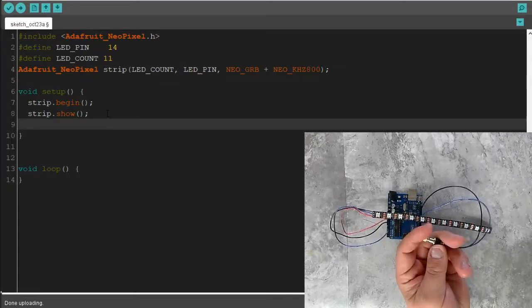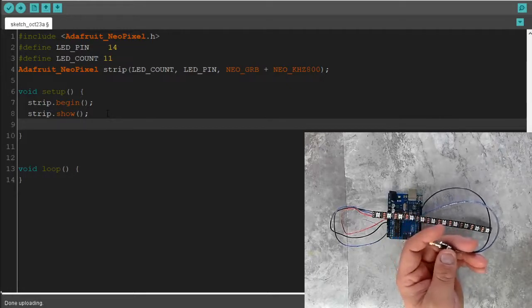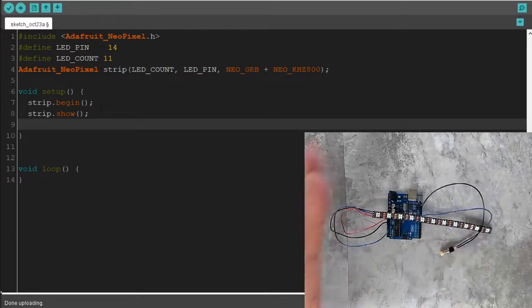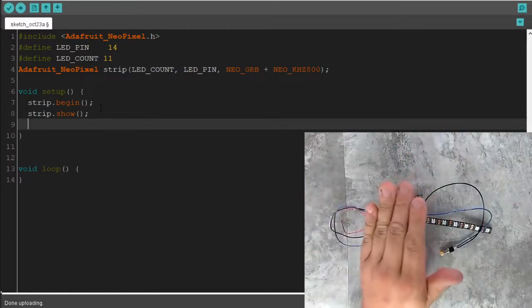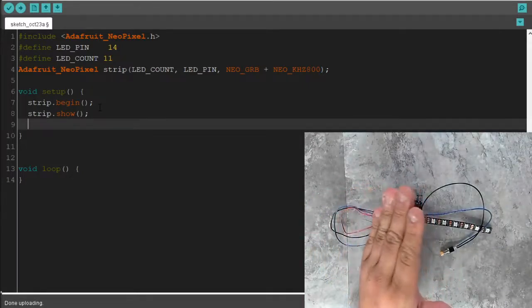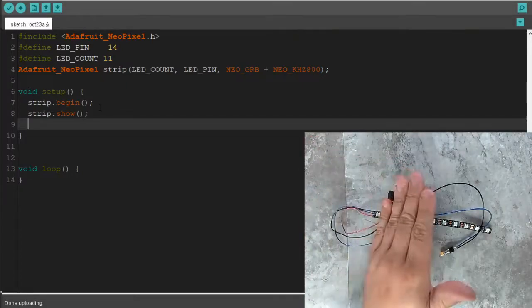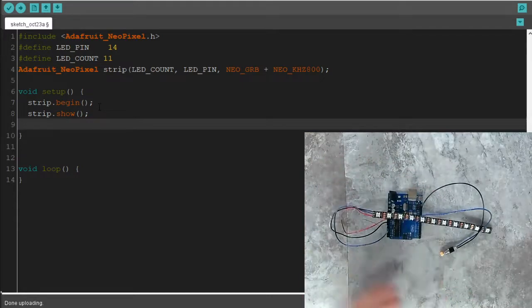I let go. You'd think that pin would just magically come back up by itself, up to 5 volts, but it doesn't. And so what it'll do, even as I put my hand near it, it'll fluctuate voltages and give me a reading of 5 volts or a reading of 0 volts, right? As I bring my hand closer and further from it. So it'll be randomly triggered, like by voltage just in the air, or if I touch it, it'll change the voltage. So what we can do in our code is pull that pin high, but very weakly.